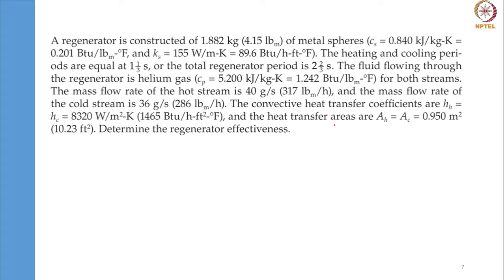So I'll give you one numerical problem to work out. We have a regenerator that is constructed with 1.88 kg of metal spheres having a specific heat of 840 joule per kg Kelvin. The thermal conductivity is also given. The heating and cooling periods are 4 by 3 seconds each, so the total regeneration period is 8 by 3 seconds. The fluid employed is helium gas, whose properties are also given.